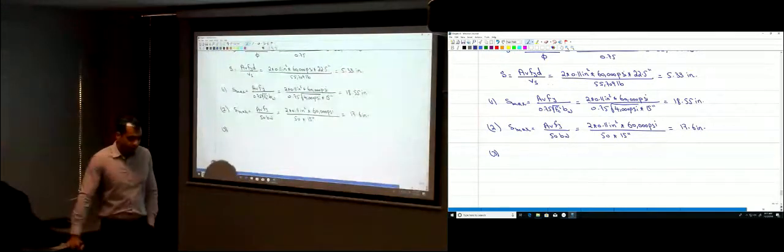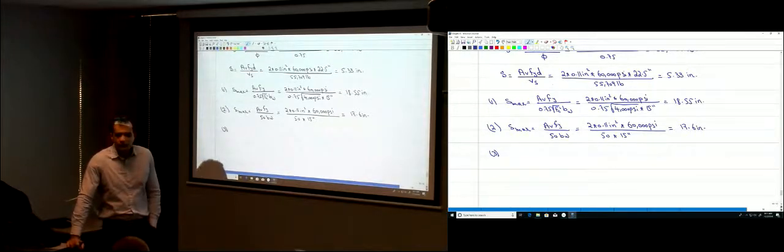What else do we have to compare with? There are another two values, either d divided by 2 or 24 inches, or d divided by 4 or 12 inches. Which one are we going to use? d divided by 2 or d divided by 4? How can you decide which one to compare with? Check 4. Exactly, I have to compare.